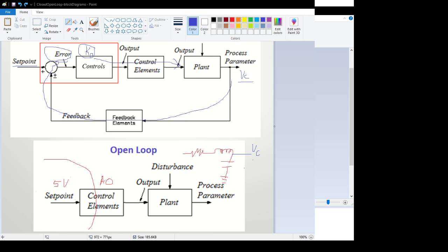All right, and then I actually have a couple other rungs here that just use a greater than, so that if the voltage across the capacitor gets above 3 volts, the amber light comes on. If it gets above 5 volts, the white light will come on. All right, and then the last thing I'm doing is, before I send my output, I'm going to scale it again into millivolts as an integer.